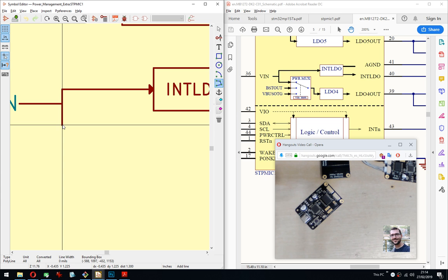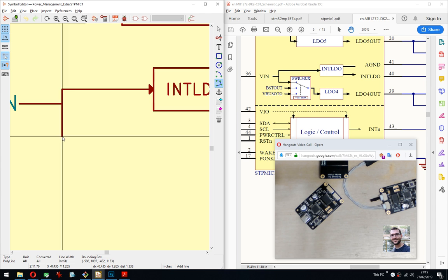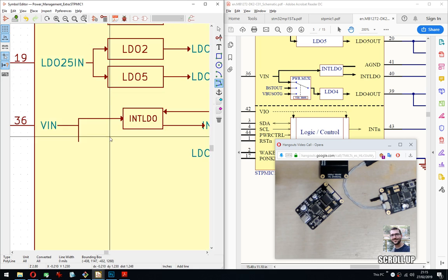Actually, that's not a bad idea. I just figured out something different. Instead of 1 probe across CAN H and CAN L, I can use 2 probes to ground. That's probably a more reliable setup than anything else. Yeah, I'll just use 2 probes instead of 1. I'm not sure if the CAN voltage is differential to each other, or actually no, it is. Never mind. It probably doesn't make a difference.